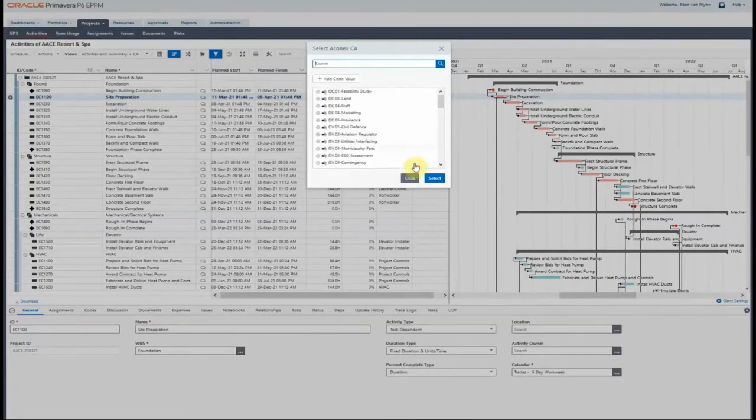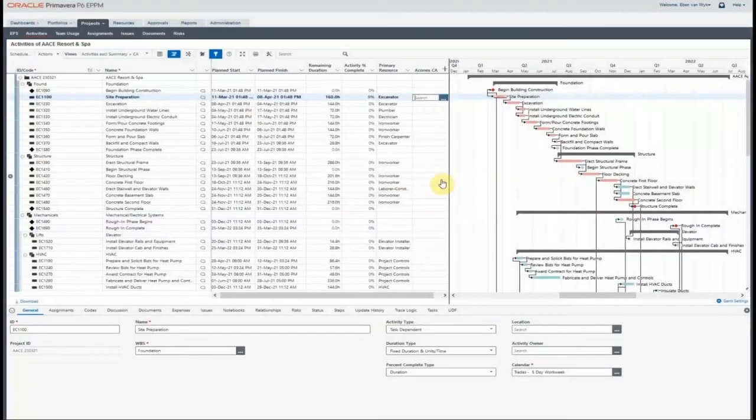to P6. Now, at this stage, I have the choice as a planner or a project manager to go and add those cost accounts to each one of my 1,000, 400,000 activities. But there's an easier way to show this and to utilize the summary activity level within P6. So what we now do is, let's go and add these summary activities to my schedule.